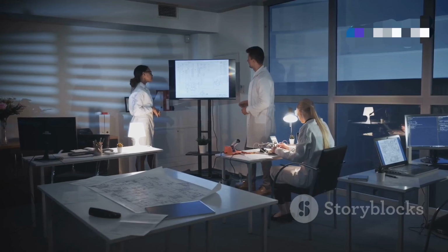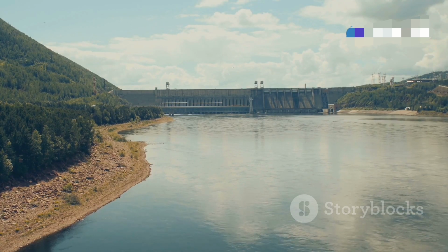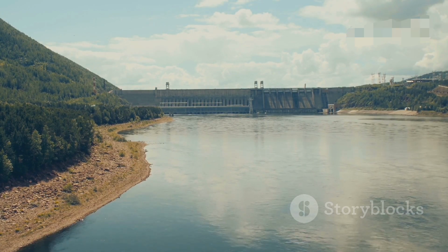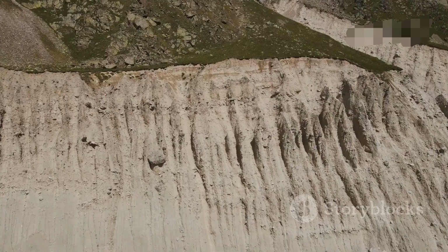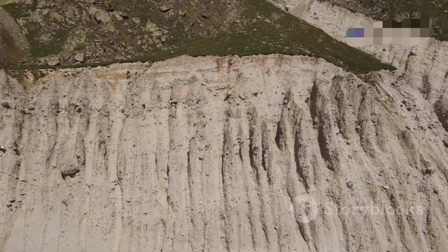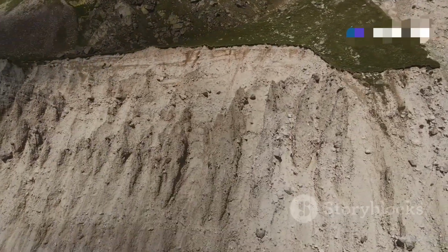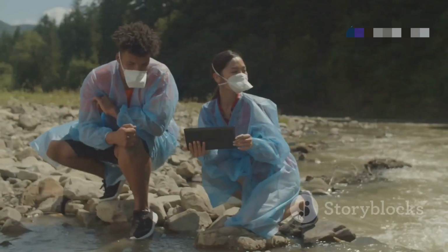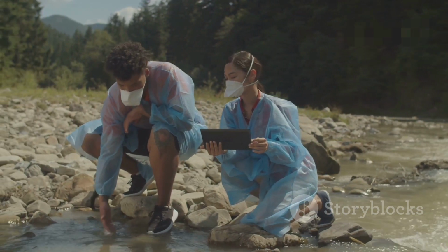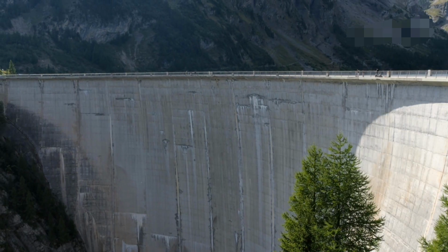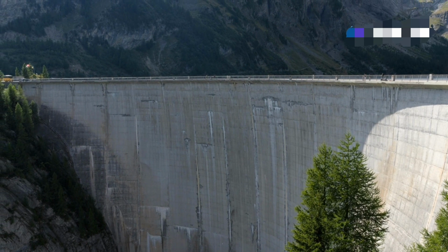While empirical equations are useful, they have limitations. They are based on a finite data set of past failures, and the specific dam being studied may have characteristics different from those in the dataset. Physical erosion models offer a more detailed approach by attempting to simulate the actual erosion processes during breach formation. These models can be more complex and require more detailed data about soil properties and hydraulics. However, they can provide valuable insights, especially for unusual dam types or conditions.